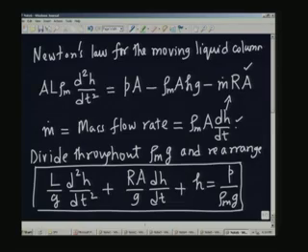So, what we notice is that it is a second order differential equation, and if you remember what we did in the case of a thermal system, we had a first order system there. First order system is governed by a first order differential equation. Here, because the equation governing the problem is a second order equation, the U tube manometer liquid is a second order system. Its motion is governed by a second order differential equation, because this is nothing but the application of Newton's laws of motion, and Newton's law will automatically bring in the second derivative, and that is what is happening here.